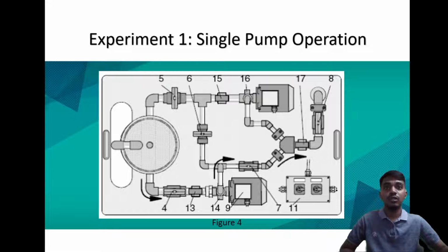Pump 1 was switched on after the main switch on the switch box. Pump 2 must remain switched off for this experiment. The volumetric flow V was set with the drain cock. Continuous inflow of water into the reservoir was ensured. P suction was measured on the intake side of the pump and P delivery was measured on the delivery side of the pump. Finally, the experiment was repeated by following the previous procedures with different volumetric flows V.